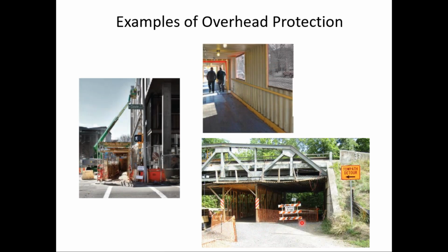There's no toe board or kick plate or base there, no detection edge. If this was my project, I would call for some sort of detectable edge or channelizer here to channelize trail users into the canopy area. Again, you can see there's signing both here and here, but that really doesn't help the visually impaired.